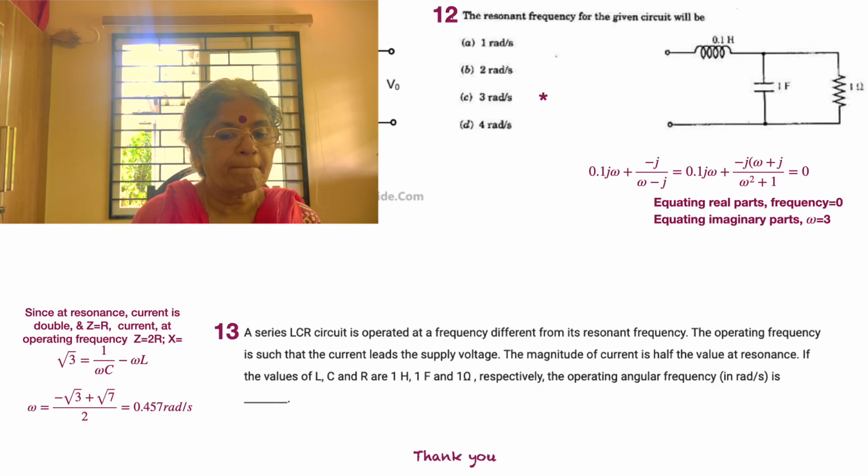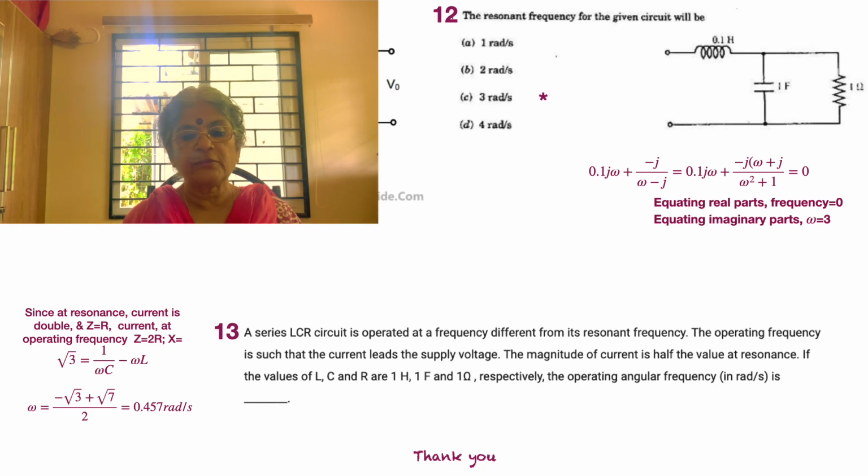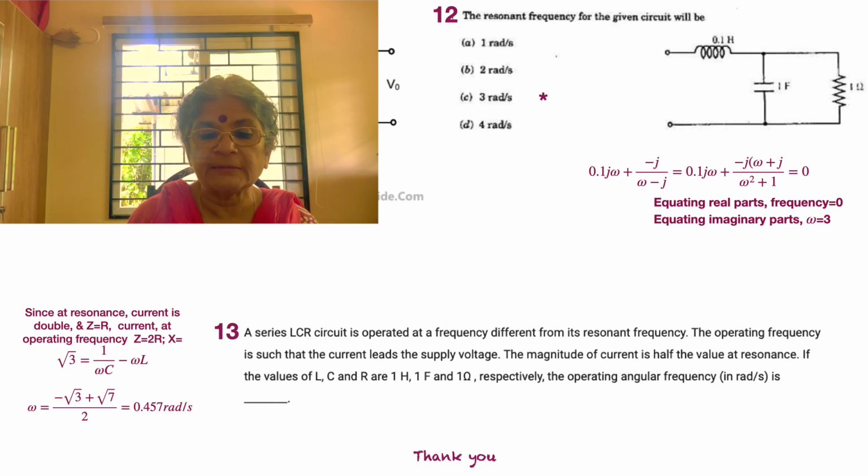Now we move on to the last problem in this session, where a series LCR circuit is operated at a frequency different from its resonant frequency. So it's a different situation, but resonant frequency is mentioned. The operating frequency is such that the current leads the supply voltage. Leading the supply voltage is also important, or in other words, the capacitive effect is prominent.